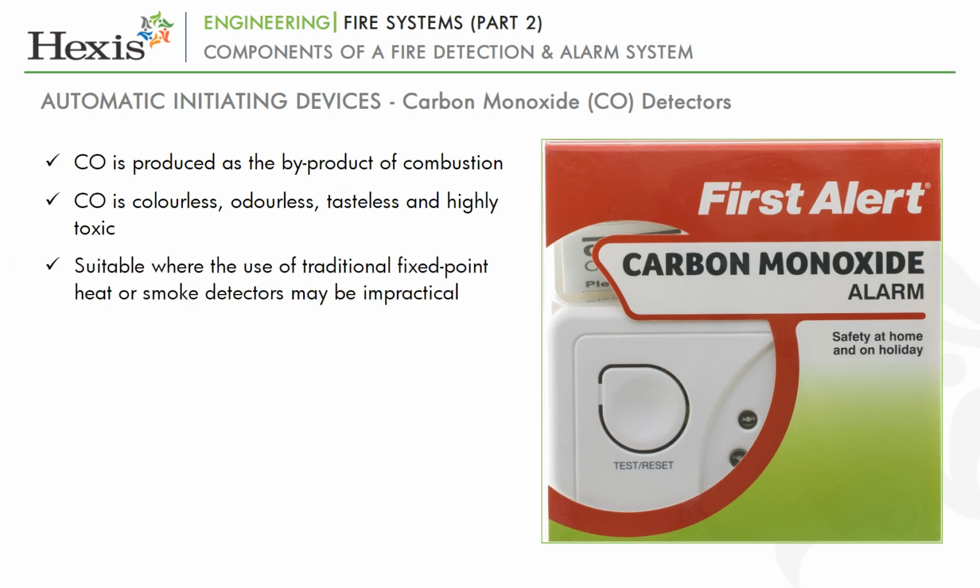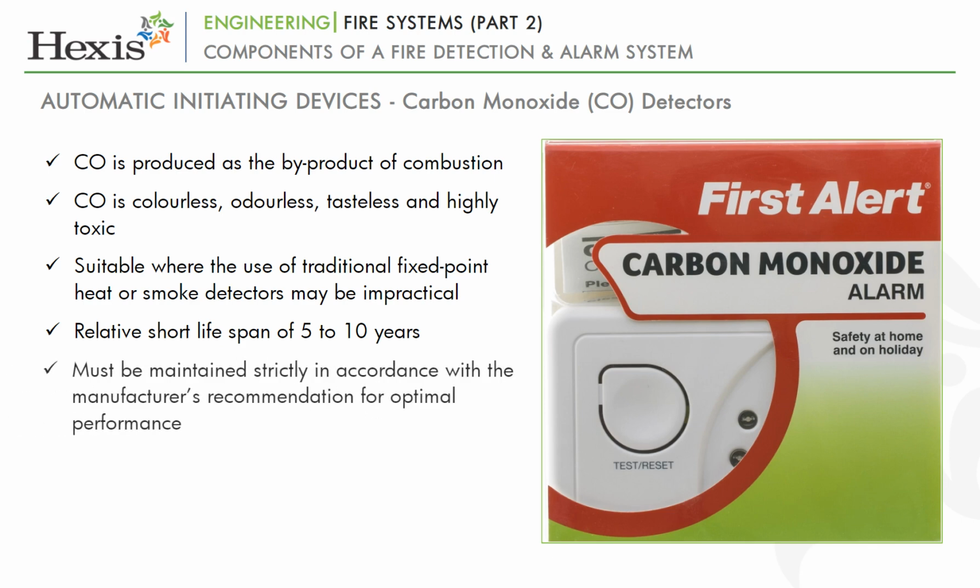Carbon monoxide fire detectors are generally suitable for a broad range of applications where the use of traditional fixed-point heat or smoke detectors may be impractical due to the presence of deceptive phenomena. Carbon monoxide fire detectors have a relatively short lifespan, 5 to 10 years, and should be maintained strictly in accordance with the manufacturer's recommendation for optimal performance.